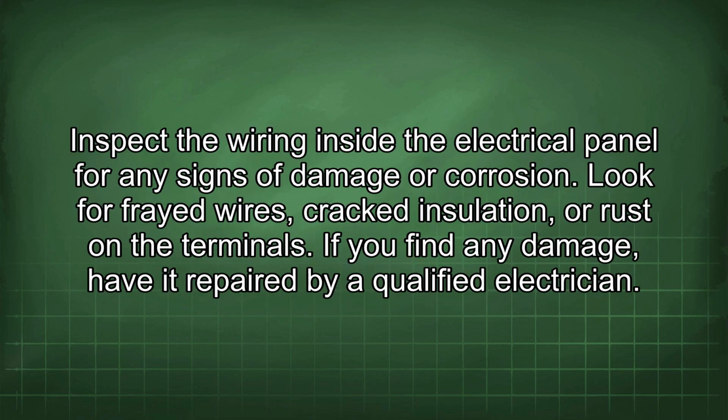them. Inspect the wiring inside the electrical panel for any signs of damage or corrosion. Look for frayed wires, cracked insulation, or rust on the terminals. If you find any damage, have it repaired by a qualified electrician.